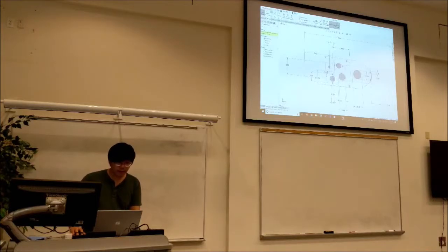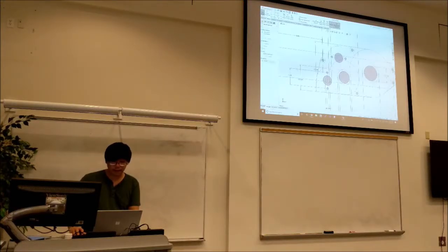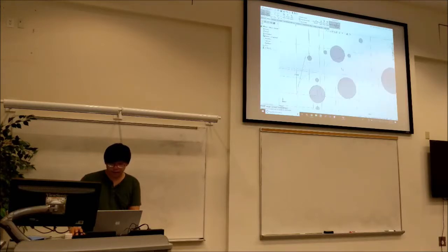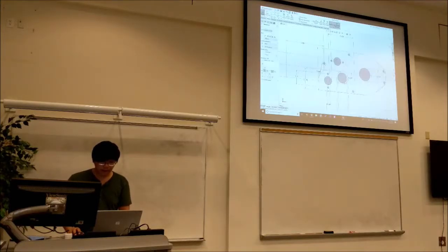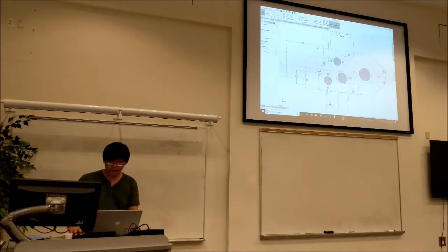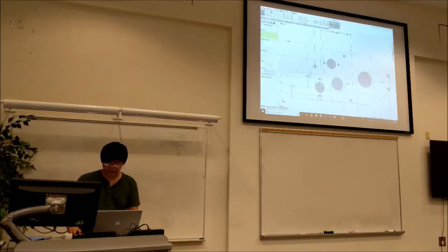And then I'm doing an infinite length line across the center of our gearbox, just to give me a place to dimension off of for angle. So you can dimension that to that. And that looks about right, so I'll just make it a nice number, 72.5 or something. So now it's slowly becoming fully defined, right? As the lines turn black, you're getting closer to having the plate finished, and we can extrude it. Now let's close off the top somehow. So we can just do a straight line across.